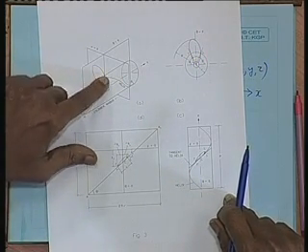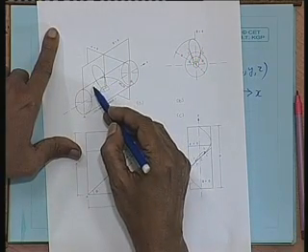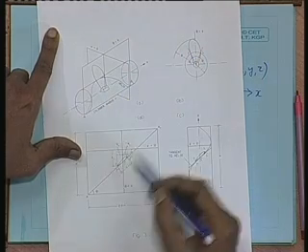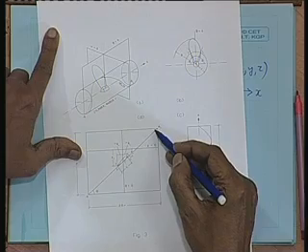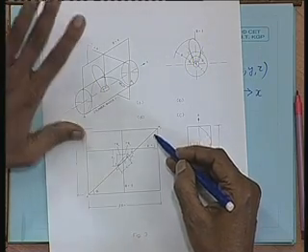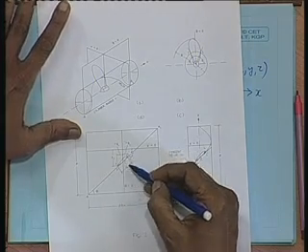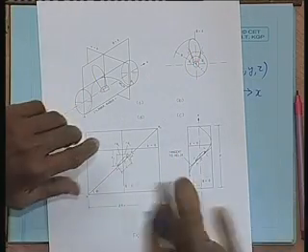Now, this section that was here, this helix that was here on this face, will now appear here on this diagonal. Correct? Now, this section that you have seen, this side is the face and this side is the back. Now, I said that the face is a part of a helicoidal surface, or at a particular radius it is a part of a helix.